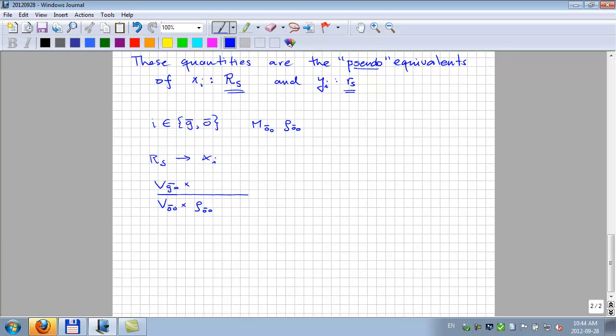Ekofisk, first big discovery, about 850 kilograms per cubic meter, okay? And now I've converted my volume of surface oil, and I'm going to do this in metric units. So I'm going to say we start with standard cubic meters per standard cubic meter, which for Ekofisk, since I started talking about Ekofisk, is about 300 standard cubic meters per standard cubic meter, Rs, just to have a number. And this was around 850, I think, kilograms per standard cubic meter, and the molecular weight was pretty close to about 200 kilograms per kilogram mole. Okay, so now I've got the ratio.